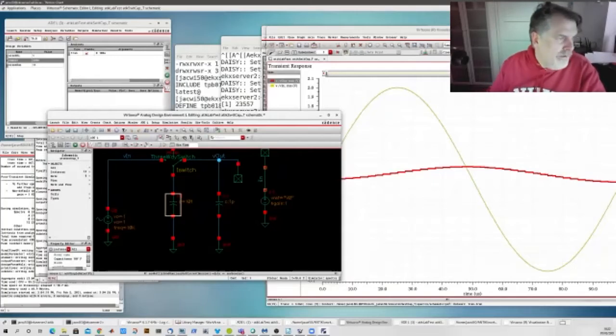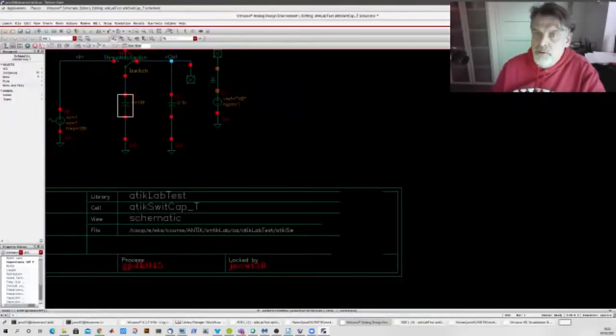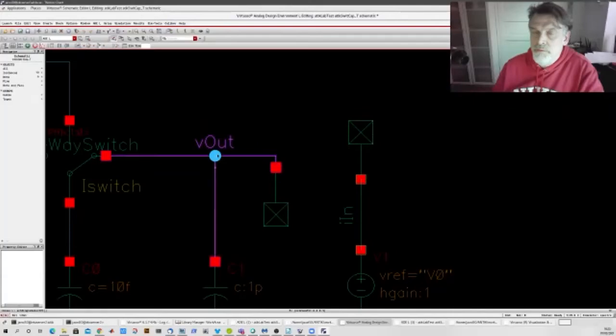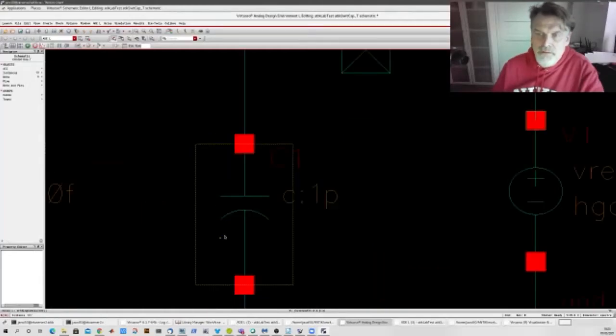So what we will do now is to start adding active circuitry. Why do we need to add active circuitry? Well, if we look at Cadence here, we see that this is quite sensitive. If I would connect an additional drive circuit on the output of this RC link, and that would have capacitance, that would influence the transfer function, because it would sum up together with this capacitor here.